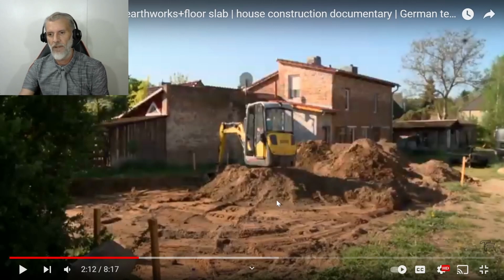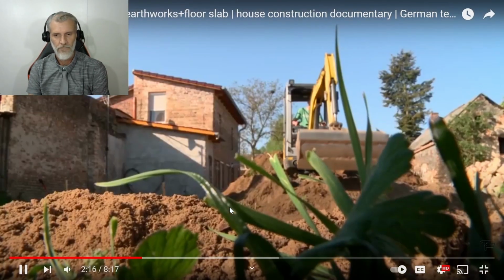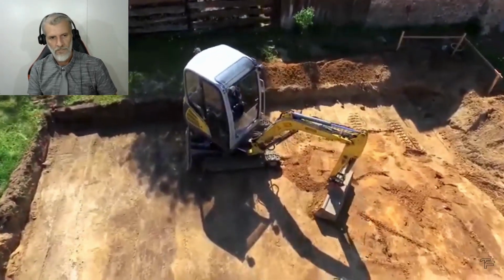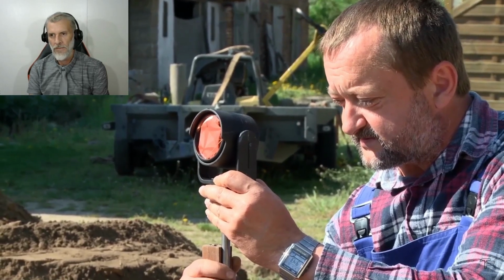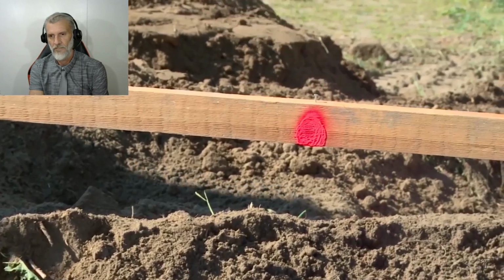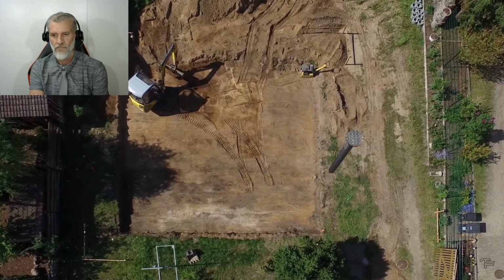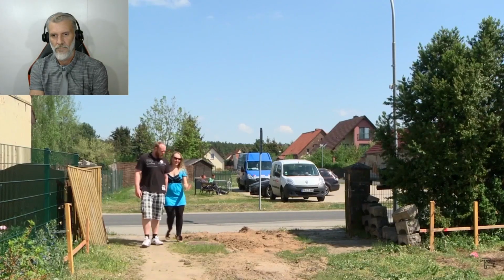So let's get started with the house in Germany. Every house needs a stable subsurface. The existing soil is removed to a depth of 50 centimeters to make room for the stable filling material, construction sand, on which the base plate will stand. The surveyors mark the dimensions of the base plate. To do this, determine the side edges and mark them with nails. A total of 8 points, which will later be connected with cords. The crossing areas of the cords are the corner points of the base plate.